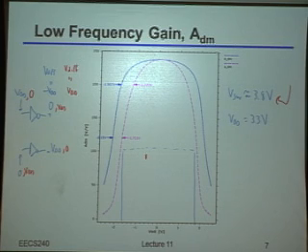Now, having said that, if we take a step back, if you remember, we had said that one of the specs that we're really going to care about was how large of a voltage swing you really could get as a function of the gain we wanted to make sure that we maintained. So as an example, in this particular case, if I wanted a small signal gain of greater than 100, we said that gave us something like 3.8 volts of swing.